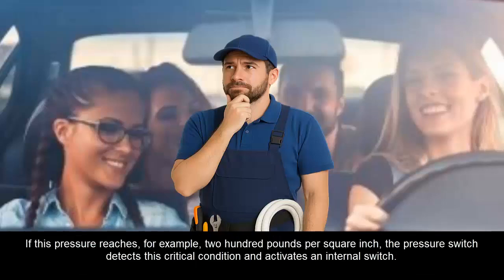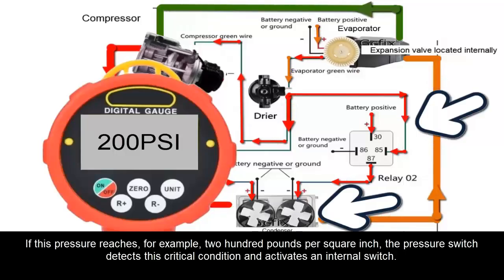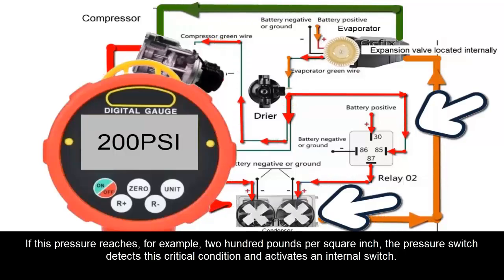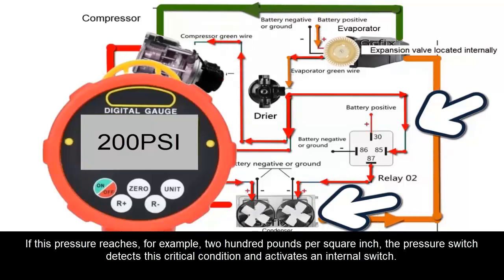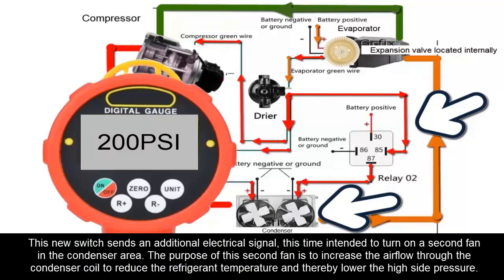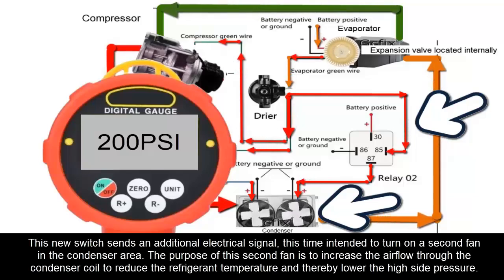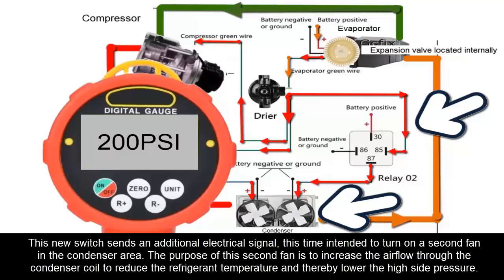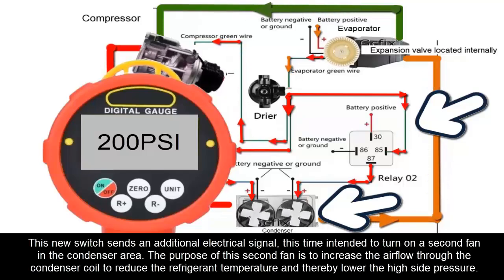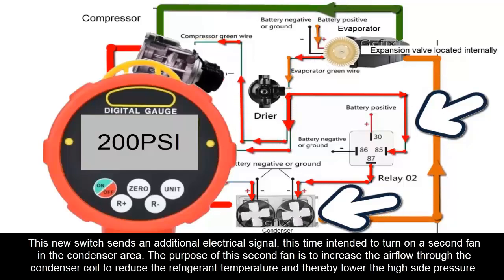If this pressure reaches, for example, 200 pounds per square inch, the pressure switch detects this critical condition and activates an internal switch. This new switch sends an additional electrical signal, this time intended to turn on a second fan in the condenser area. The purpose of this second fan is to increase the airflow through the condenser coil to reduce the refrigerant temperature and thereby lower the high side pressure.